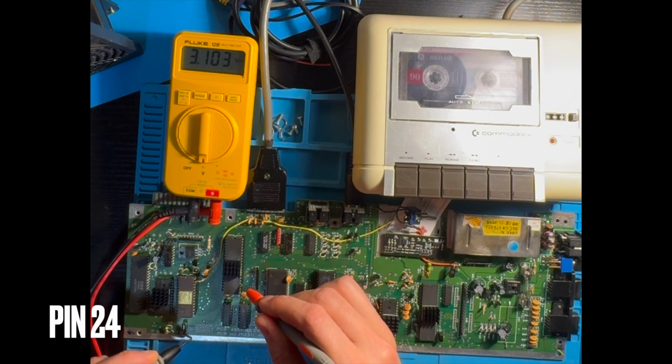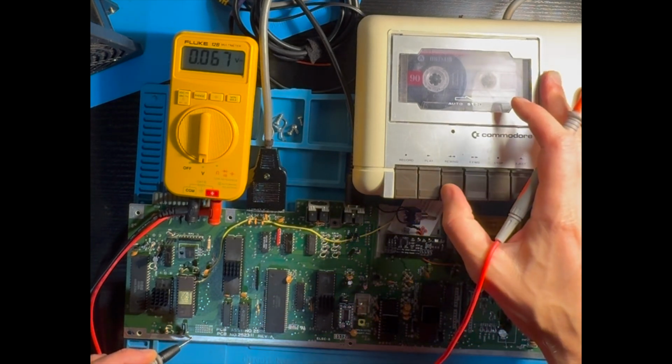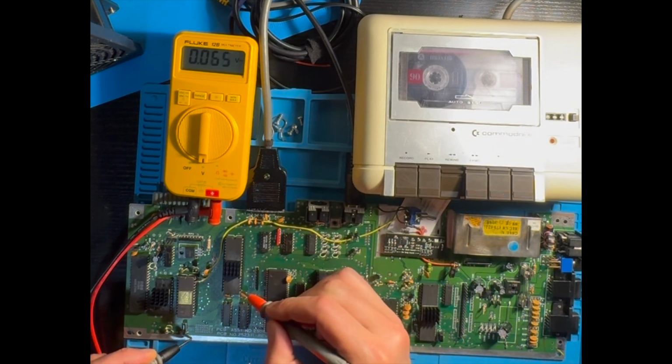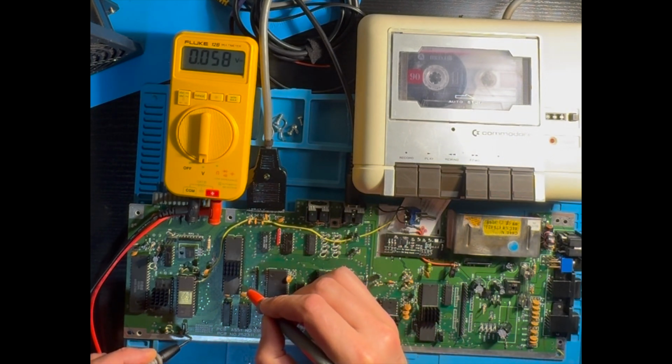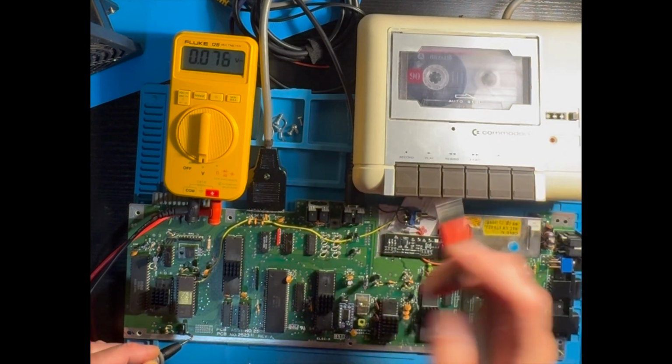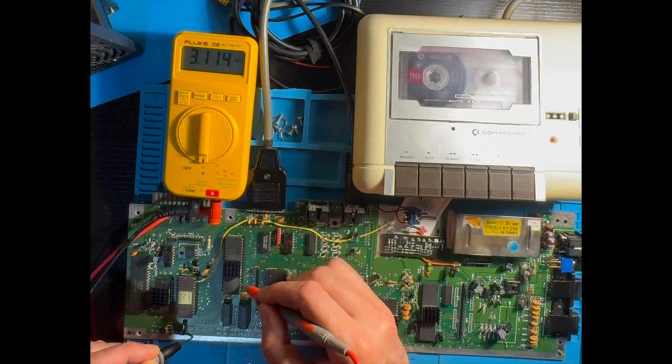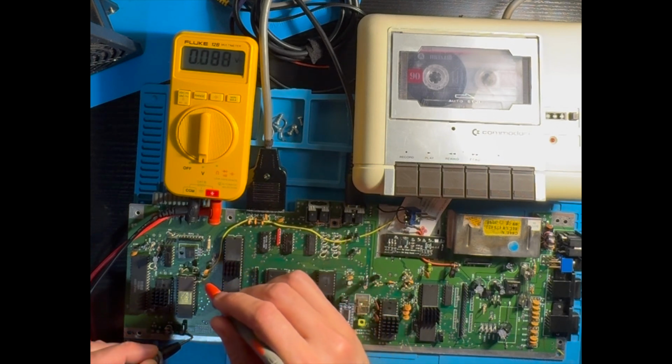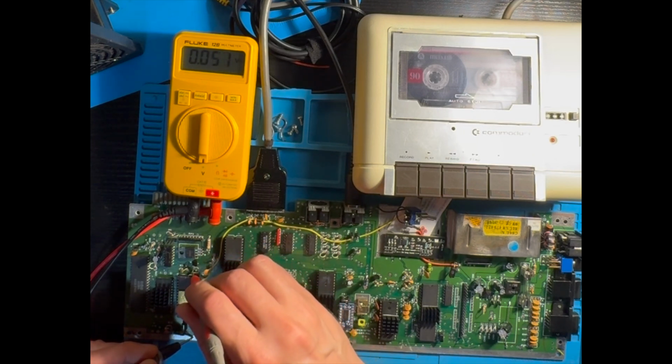and I'm going to just look, and now we're at 3 volts. So I'm like, okay, 3 volts, and now I'm going to hit rewind, for example, and it goes down. So it goes from high to low voltage. That seems normal to me. I think that's perfectly fine. And if I turn it off again and try it again, yep, back to 3 volts. So I'm pretty sure at this point the CPU is in good shape, which is awesome.